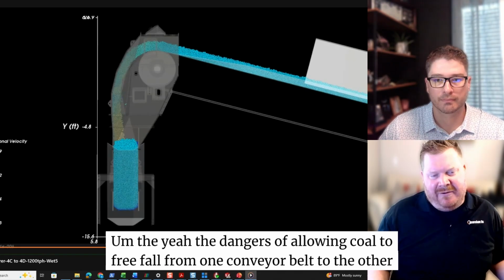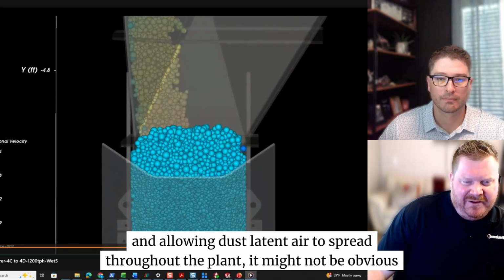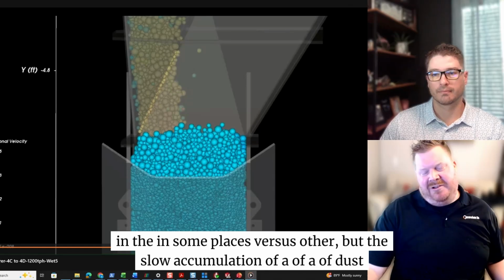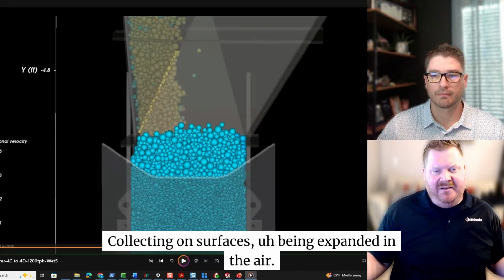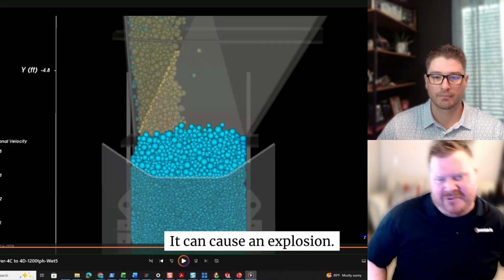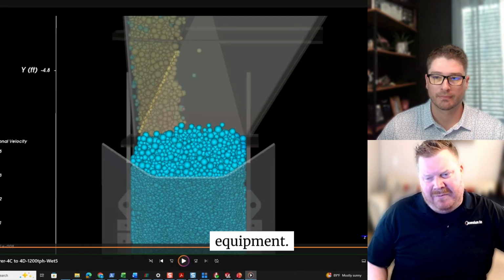The dangers of allowing coal to free fall from one conveyor belt to the other and allowing dust-laden air to spread throughout the plant might not be obvious in some places versus others, but there's the slow accumulation of dust collecting on surfaces and being expanded in the air. There are a multitude of health issues with that. It can cause an explosion if the air touches any sort of hot piece of equipment.